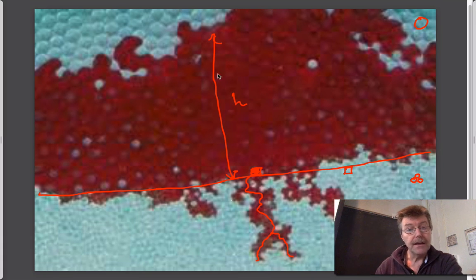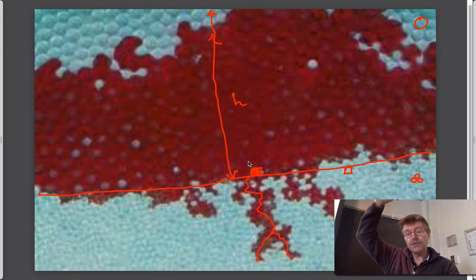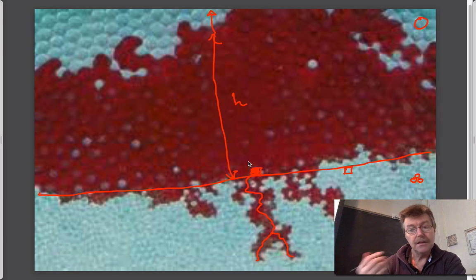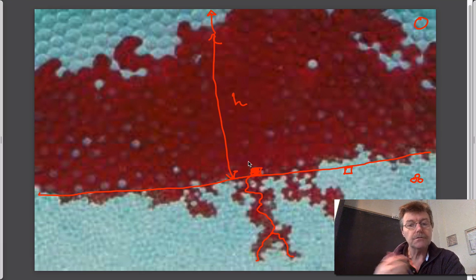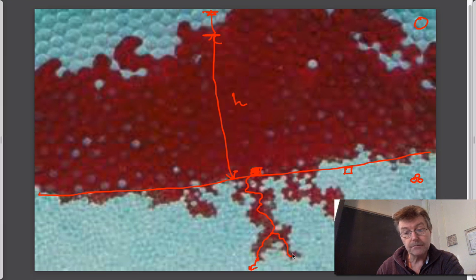You could imagine that if you boosted up this height here, you'd increase the pressure here, just like the pressure you'd feel at the bottom of a swimming pool as you make it deeper. Ignore the fact that it's in a porous medium. It's like a swimming pool that's just filled with sand. It doesn't make any difference to the fluid pressure you'd feel if you're sitting on the bottom of the swimming pool. So if you increase this pressure or head by some amount, then maybe this would keep on going a certain amount, and maybe some boundaries here that weren't activated originally actually come up with filling up the pore space. That's the process that we're looking to understand.